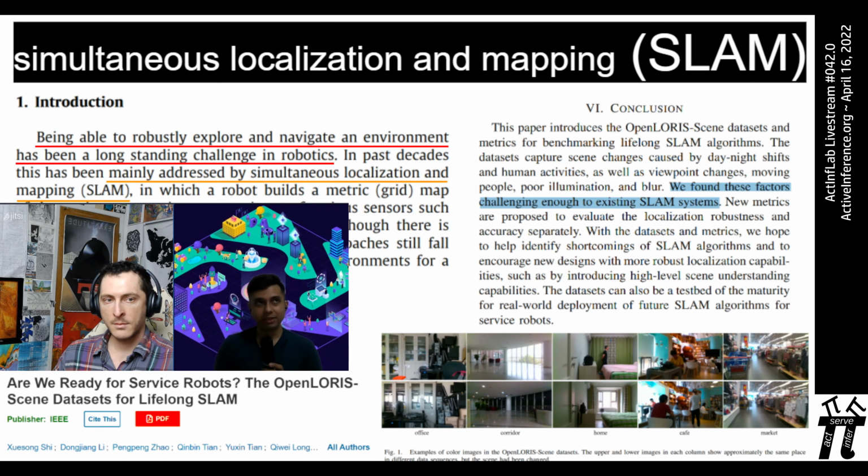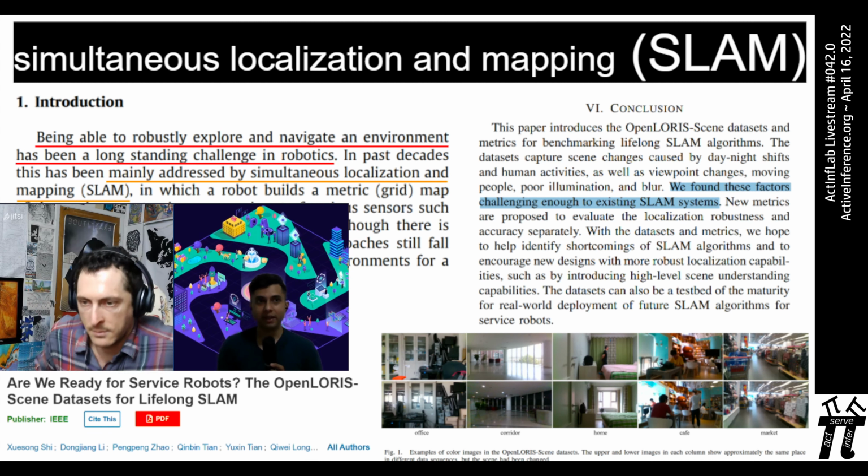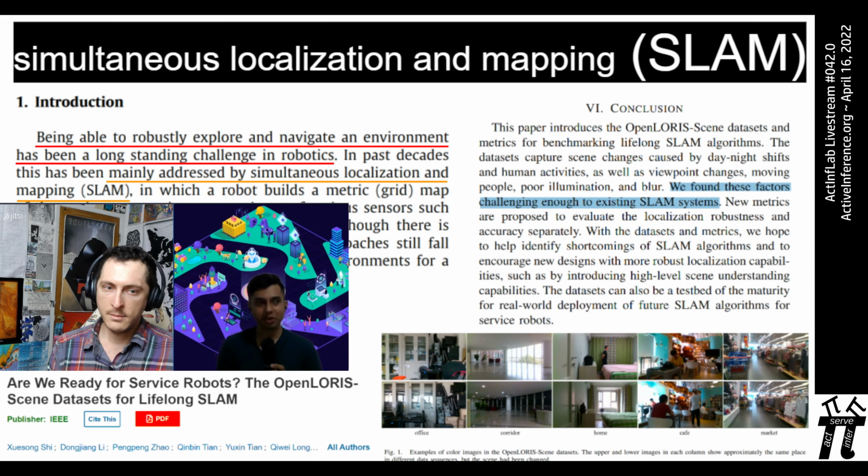But that dynamic organization poses a lot of challenges to traditional SLAM techniques, such as changing even one thing in that environment can greatly modify what map the robot had made. You can imagine there's a map, and you had localized your position with reference to particular objects in the map, and then you move those objects. So the robot's world just shifted all around it, literally. That simple change might be very obvious for humans to detect, but for a robot which is using those reference points to localize itself in the world and construct the map out of it,